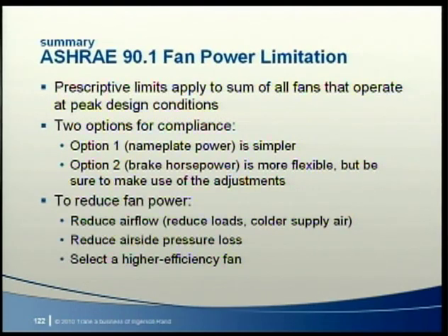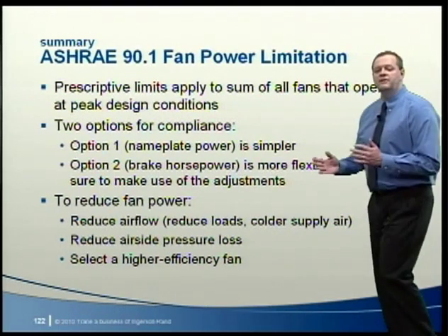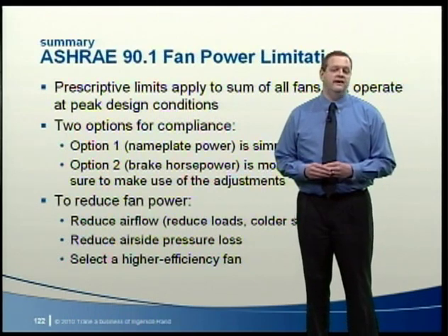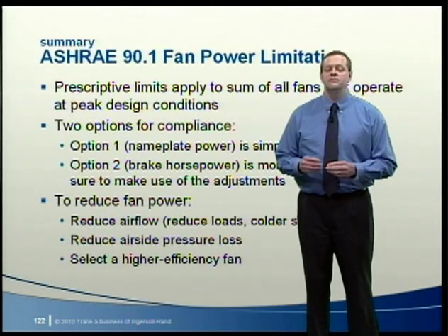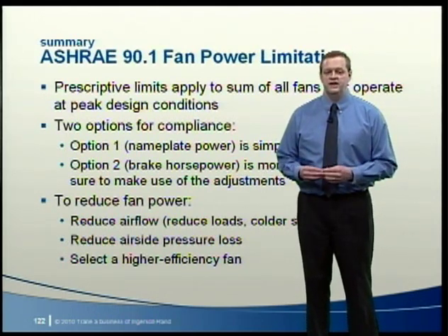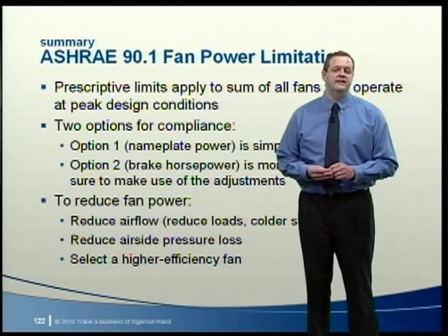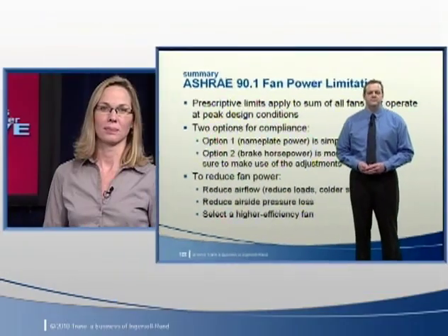Finally, if you need to decrease fan power, look for ways to reduce airflow by reducing the cooling load or designing for a colder supply temperature, reduce airside pressure losses, and/or select a higher efficiency fan. Incidentally, AMCA has been working on a new standard, 205, which helps to more clearly classify fan efficiency. So you may start to hear the term fan efficiency grade, and it's possible that it might make its way into minimum efficiency standards like 90.1 sometime in the future.